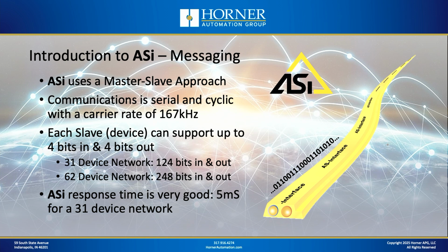That's another unique thing about ASi. ASi doesn't try and be everything to everybody. It's basically focused on simple sensors and simple actuators. So 4 bits in and 4 bits out for a sensor or an actuator is plenty in most cases. I mean, let's face it, if you hardwire a sensor or actuator back to a PLC input or output, you're at 1 bit per device, typically, if you're talking about a digital device. So again, that's one of the other things about ASi. It's focused on sensors and actuators.